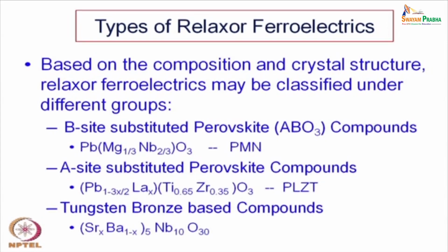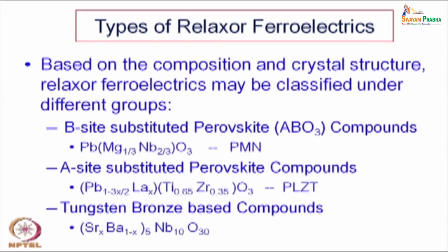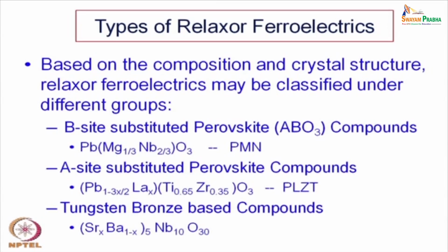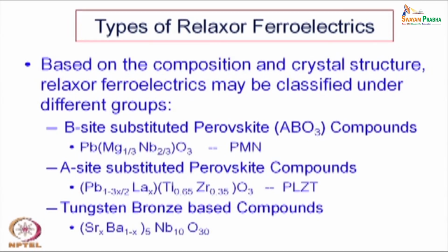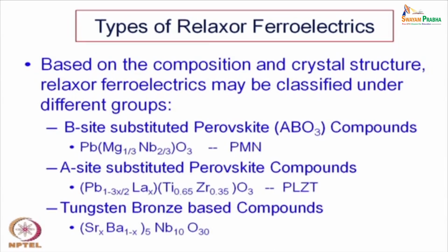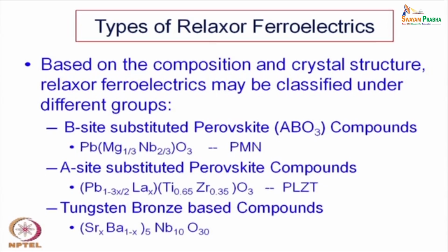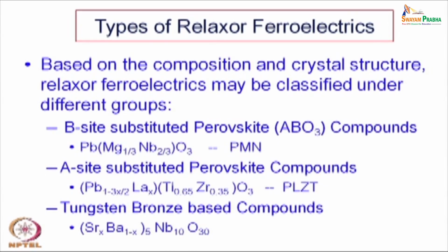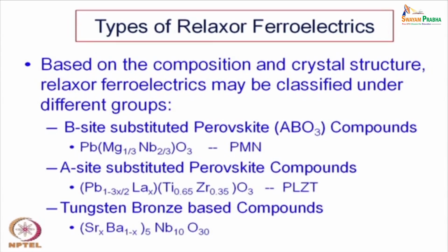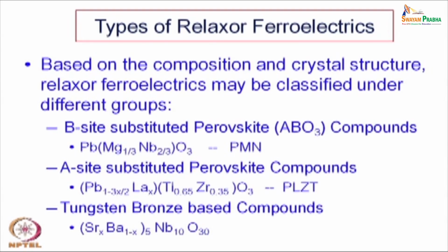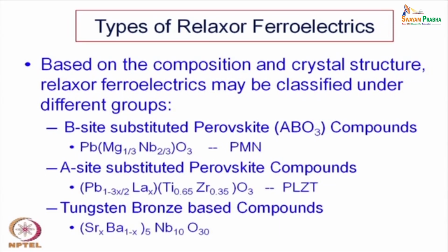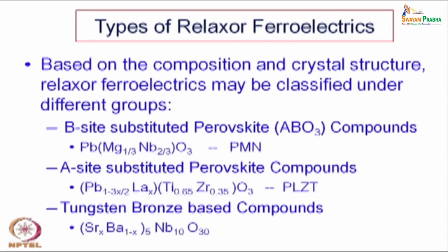It is not at the morphotropic phase boundary, but away from it, with 65 mole percent of lead titanate and 35 mole percent of lead zirconate.